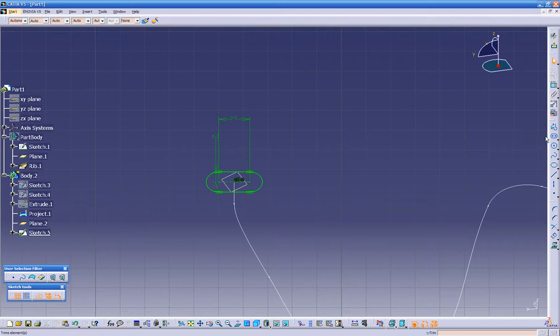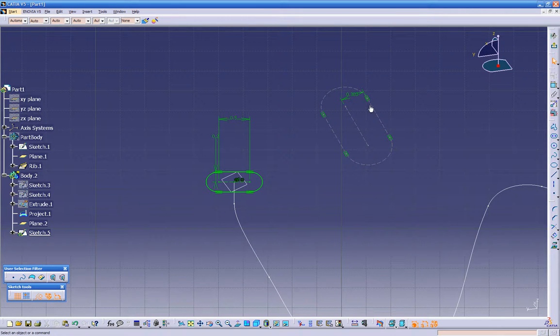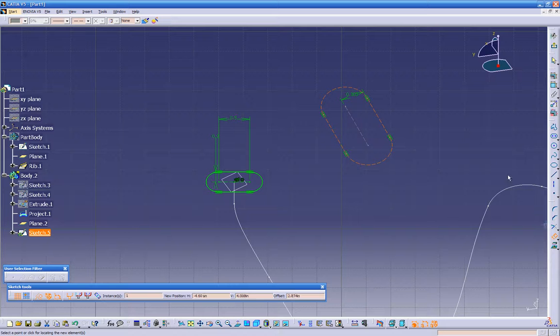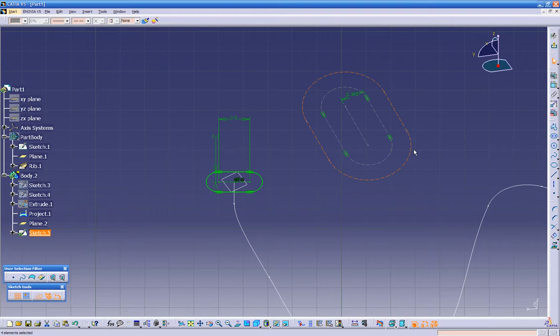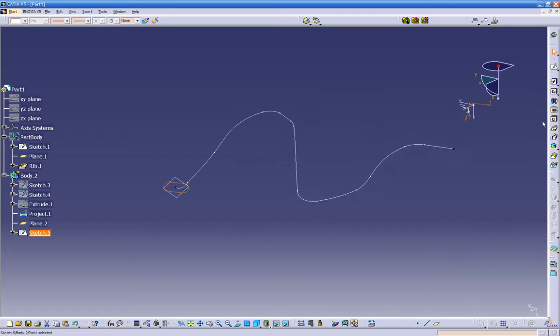What I was gonna show you over here by this offset, just highlight the stuff that you want to offset. Just click on this option right here, and you can go bigger or smaller. Or if you hit the tab key, you're gonna come down here and make it 0.300 and click OK, and that's our dimension right there. So that's offset, but we don't need this anymore. So let's get out of here. Let's go on a rib and give it another try.